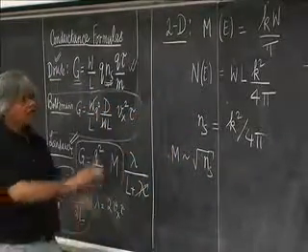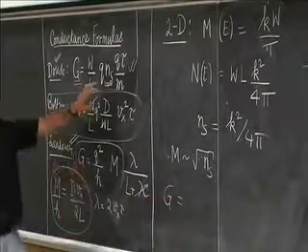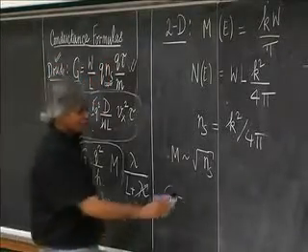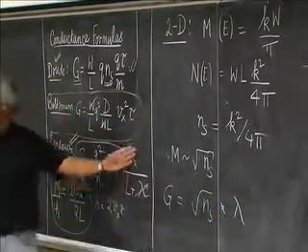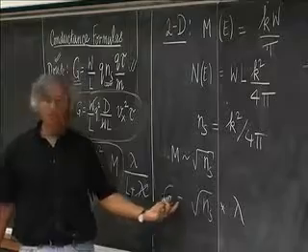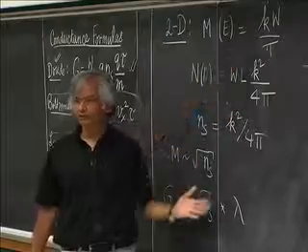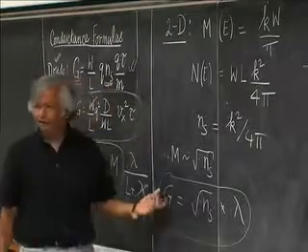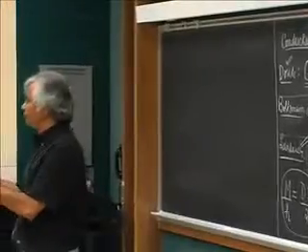And so from this point of view, when you write the conductance, instead of ns times something that you call mobility, you tend to get square root of ns times this mean free path. The square root of ns is simply because it's proportional to the number of modes, and ns is proportional to k square, m is proportional to k. So if you believe this, then when you measure conductivity, you'd want to divide it by square root of ns, and then whatever you get, you try to interpret as mean free path and make sense of it.